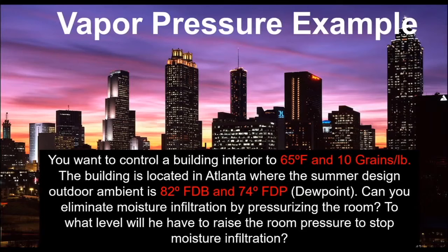Let's take a look at an example that would help you understand the significant force that vapor pressure is. Let's say that we want to control a building interior to 65 degrees Fahrenheit and 10 grains. That might be some sort of archival storage system. Let's put this building in Atlanta, where the summer design ambient condition is 82 degrees dry bulb and 74 dew point. Let's ask ourselves the question, can you eliminate moisture infiltration by pressurizing the room?